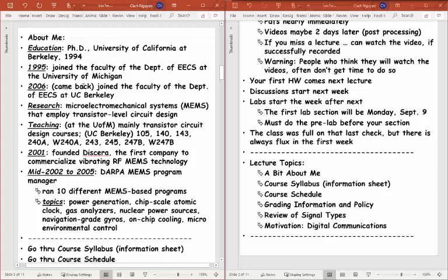My research is on microelectromechanical systems. So this is actually tiny mechanical devices that physically move on a wafer. You can integrate some of them with transistors, and they can do things like create sensors, like in your automobile, for example. When your automobile crashes, I hope it doesn't, the sensor that deploys your airbag is a MEMS sensor. Even in your phones, if you rotate your phone from landscape to portrait, there's a MEMS accelerometer in there and maybe a gyroscope that will detect that you've rotated it, and that's how it knows it's rotated, and it can then change your screen from landscape to portrait.